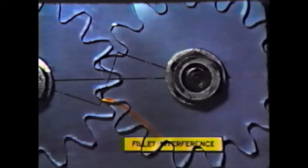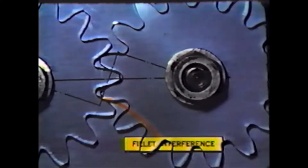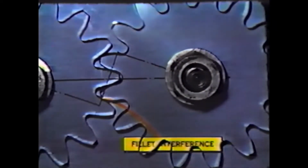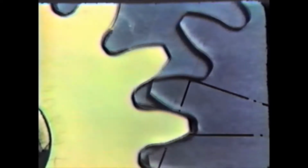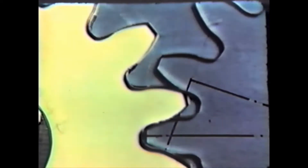Another condition, fillet interference, here exaggerated, results from the fillet interfering with the tip of the mating tooth. This prevents the transmission of uniform angular velocity. A paper template of this gear with the high fillet placed behind a properly generated gear shows the amount of material that had to be removed to avoid fillet interference.